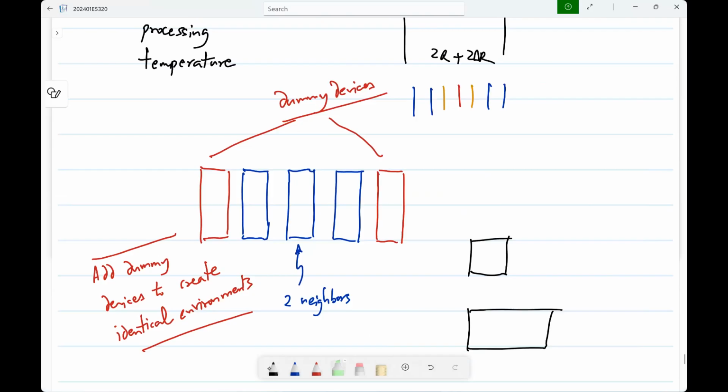No, it does, right? Even with the asymmetrical environment, the effect of temperature could also be different. They're all difficult to predict. But gradient is different. Gradient is when they have different temperatures and you want to have identical values, then you have to use common centroid.